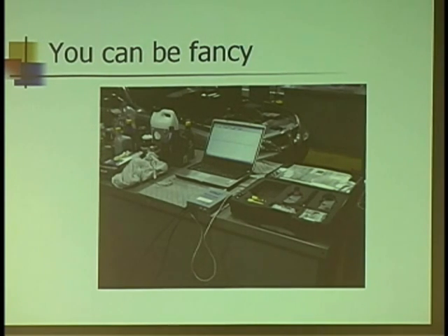Barney's tools, very user-friendly. Personally, I've never needed 8 channels. But there's a lot of things that scope will do for you, like the in-cylinder pressure testing. It'll do the diagnostics for you. It'll tell you where the problem is. The Pico, I think, is probably one of the more affordable on the market, but it doesn't have all the bells and whistles. But if you can read a schematic and you know how to hook up a multimeter, it's a very powerful scope. I can record literally hours of data and do it in a manner that allows me to zoom in on minute sections of it with accuracy.